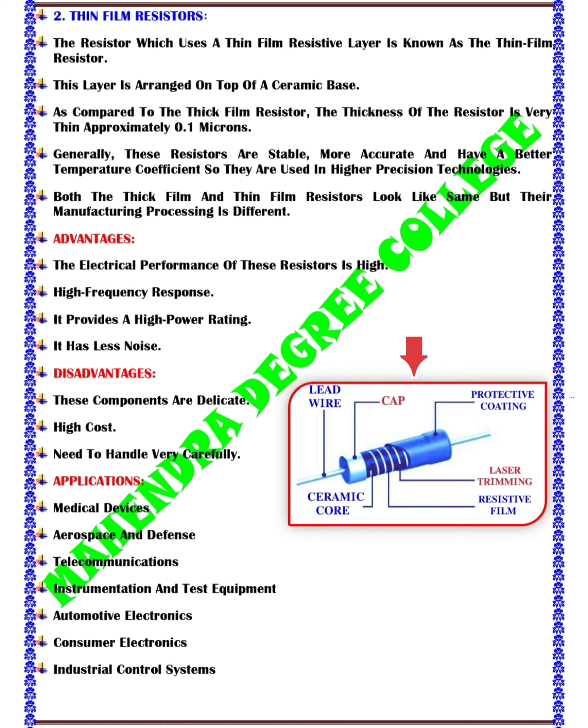The construction of the film resistor can be done through a sputtering process of the resistive material over the ceramic. After that, the surface can be etched through ultraviolet exposure and required etching techniques. This resistor uses different materials while making, like bismuth ruthenate, tantalum nitride, lead oxide, nickel chromium and ruthenium oxide.